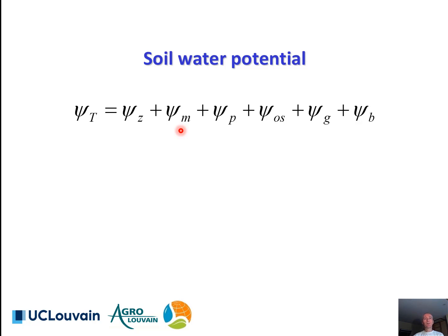Another force that can be present in the soil is the hydrostatic force. If a water particle is situated in a saturated soil system, and this saturated soil system resides on top of an impermeable, flow-resisting soil layer, then a hydrostatic pressure can build up in the saturated soil water body. In such cases, the water pressure in the soil body will become positive, and it measures the pressure exerted by the water layers on top of the considered water particle. Hence, in a saturated soil water layer, a positive component of the water potential develops, psi-p. This component will be absent in an unsaturated soil layer.